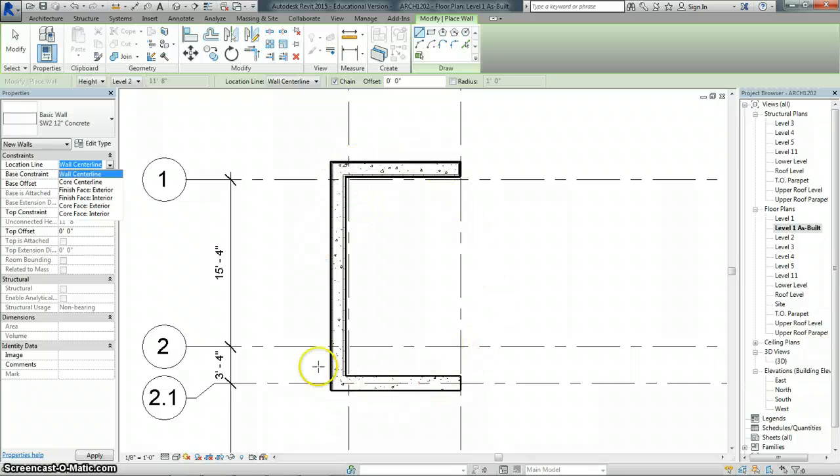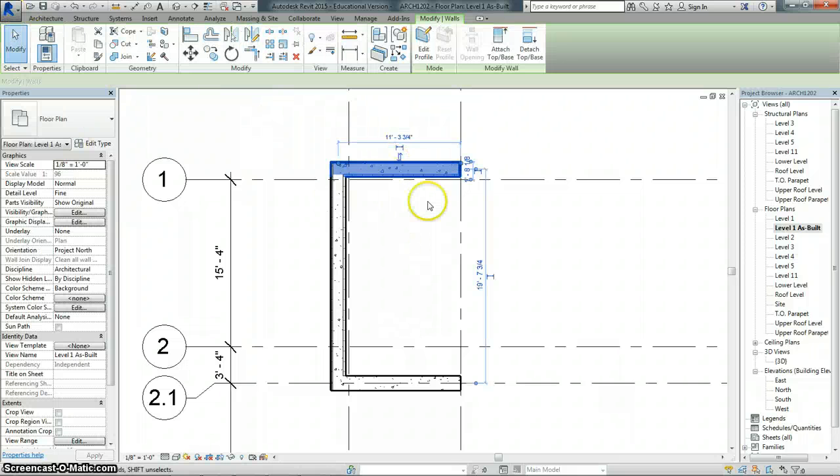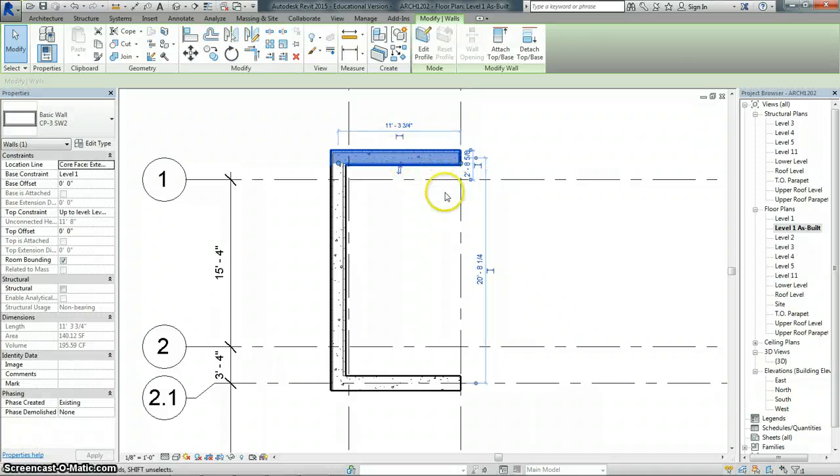Now one of the things you remember we talked about as we place things, when you're placing a wall, it's kind of clockwise. That's how, if you install a wall, then you know that the outside face will be the exterior. If you go the other direction, they'll flip, but you can easily fix that. I'll show you here. If you do go the wrong direction, not a big deal. Just have to go up here. You see these little buttons. You just flip the wall. So basically that reference changes.